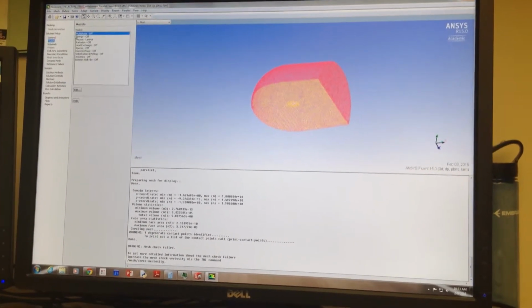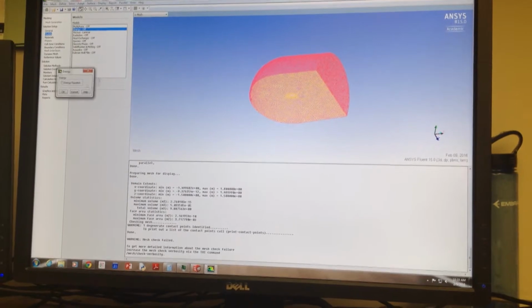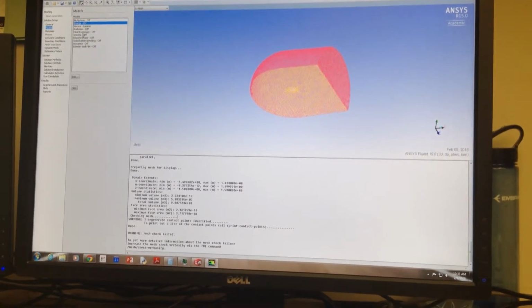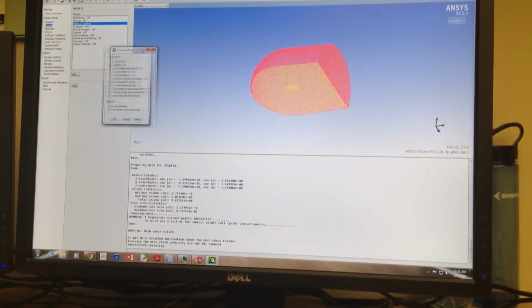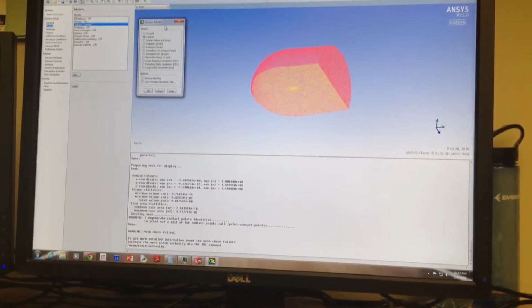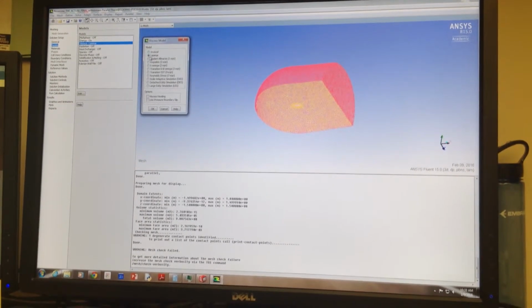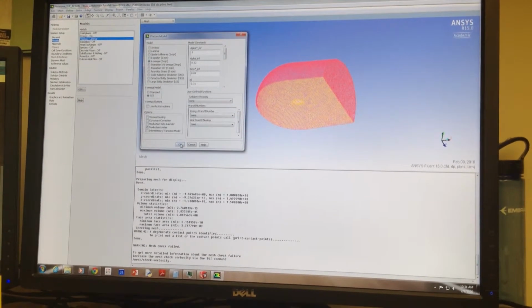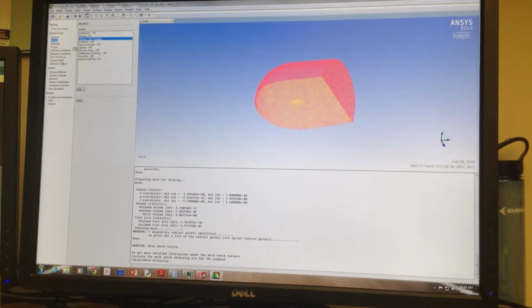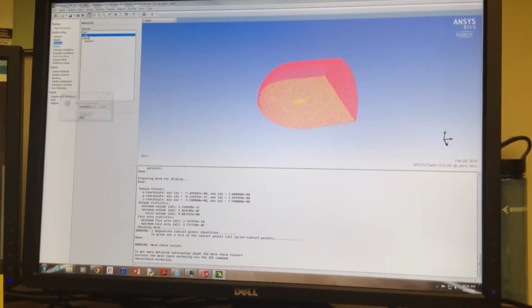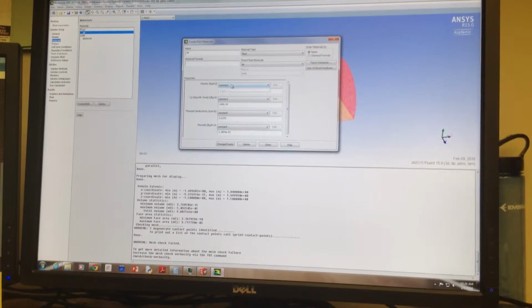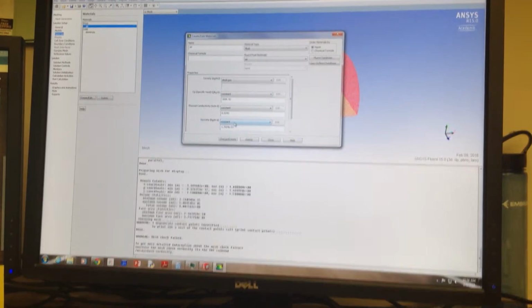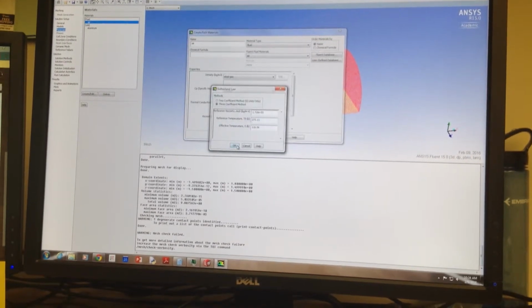Click on Models. It would be energy one, equation zero, zero, five. Double click. Is it this? Yes. Click on this one, k-omega, go for SST. Okay, materials: you know, air. Double click on that. It's ideal gas, viscosity Sutherland.